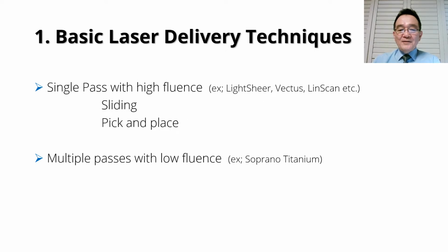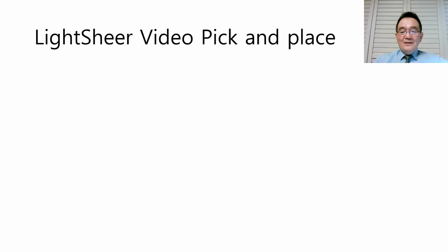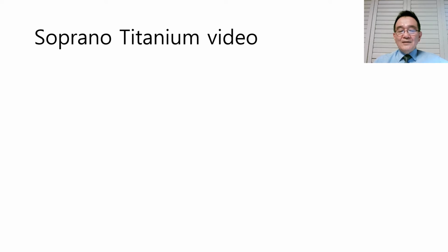There are 2 basic laser delivery techniques. The first one is single pass with high fluence. The second is multiple passes with low fluence. The single pass technique is divided into sliding and pick and place techniques. This video shows a single pass technique with the pick and place method. This video shows multiple passes with low fluence.